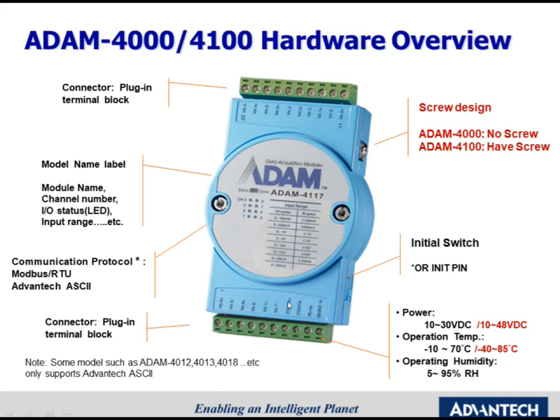There are two pins, VS plus and ground pin, for power input. For ADAM 4000, the power input range is from 10 to 30 volt. But for ADAM 4100, the power input range is wider, from 10 to 48 volt. The operating temperature is also wider in ADAM 4100, from -40 to 85 Celsius degrees.